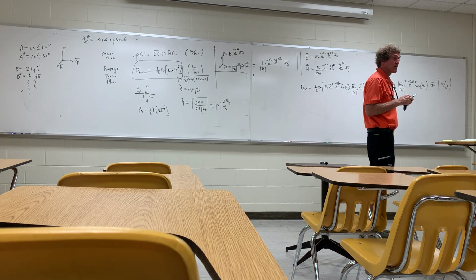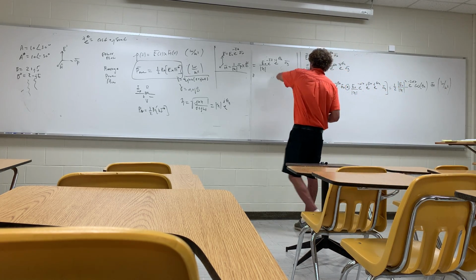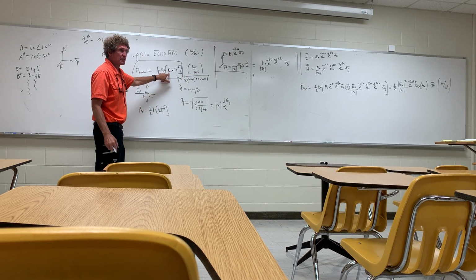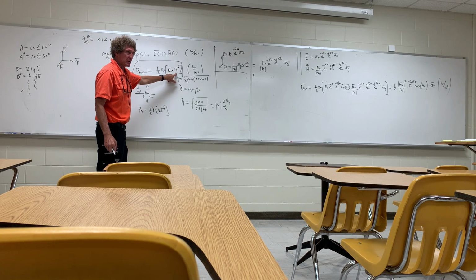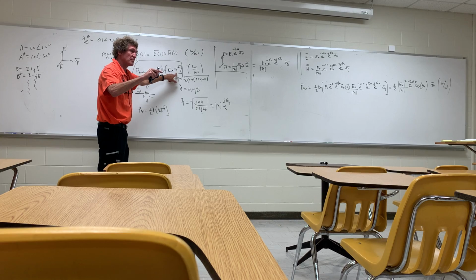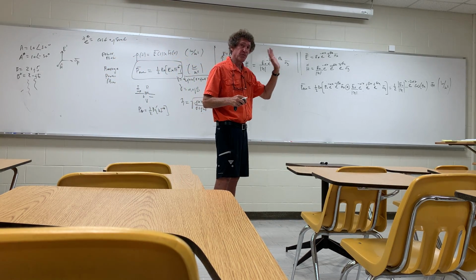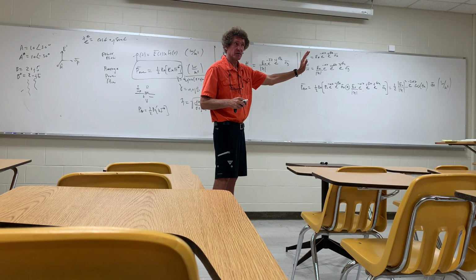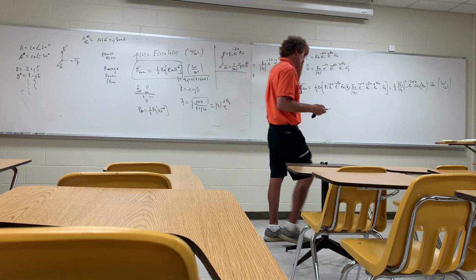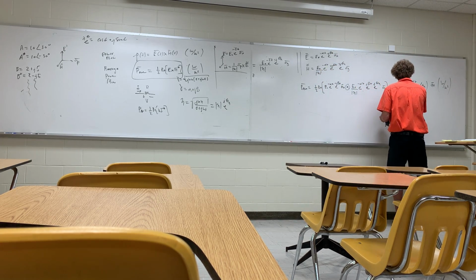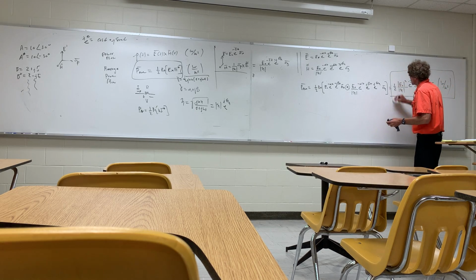Could you explain the units a little bit more? Why it's watts per meter squared? Sure. If you take a look at this, E field is volts per meter, right? H field is amps per meter. Volt amps is watts per meter squared, and that's power flow. That's flowing, it's not being dissipated. Y'all follow me? There is going to be power dissipation, we'll talk about it a bit. So that's the average power flow right here, and this is the one that's generally true.